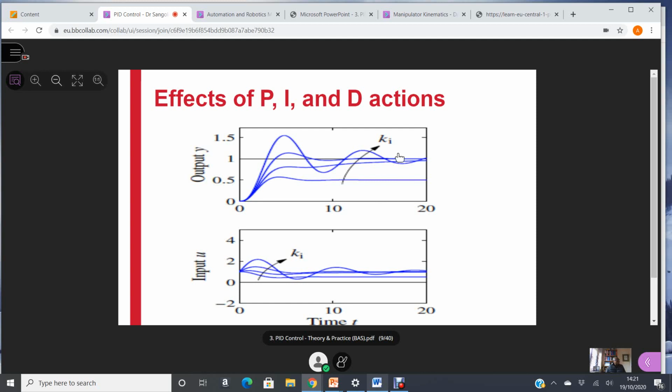Ki is 0, and then as you increase Ki, you see that now the final value will match the step input, which means steady state error will be 0. So as long as your Ki is not 0, then your steady state error is eliminated. That is the main use of integral action, to eliminate any steady state error in the step response of any system. Very, very good benefit. One better than the proportional control, which only reduces but never actually eliminates the steady state error.